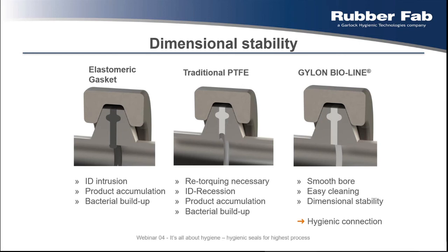Whereas most traditional PTFE is compressed in a cylinder in its raw form and then sintered in a whole block, the GYLON materials are manufactured completely differently. With GYLON, we are talking about a completely different mixing process of raw materials and a so-called calendering process, meaning the materials are rolled out in enormous calendering equipment with a lot of force.